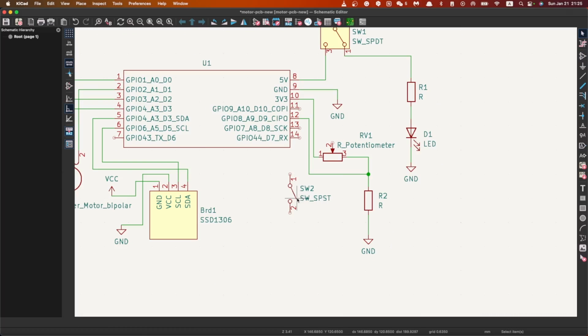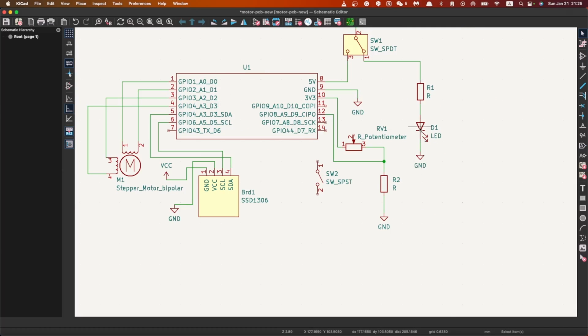If we are pressing it, then this thing is being pushed to pin 2, and this circuit is closed or connected. And if we are not pushing it, it is open or disconnected. All right. And for better debugging of our circuit, I would like another LED here to show whether the button is being pressed or not. And since we are using an LED, we need a protecting resistor there to control the current of that part of the circuit.